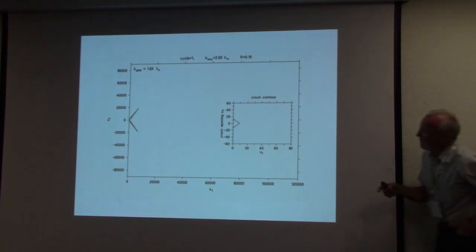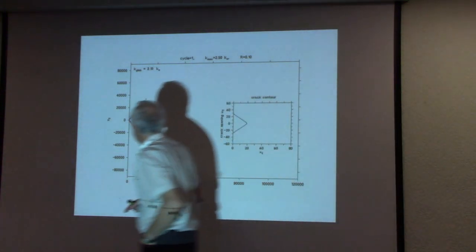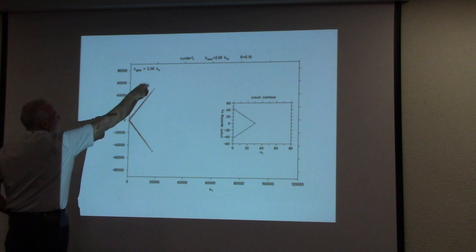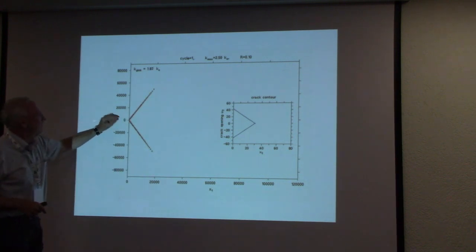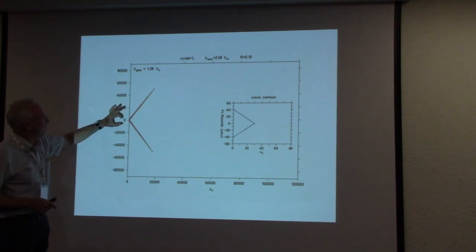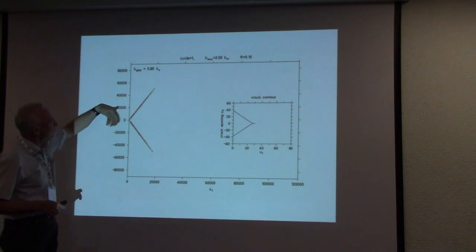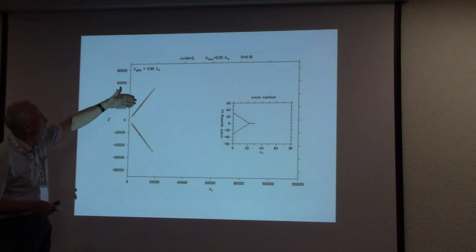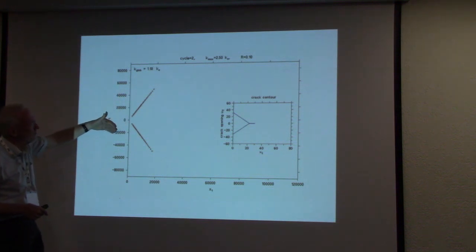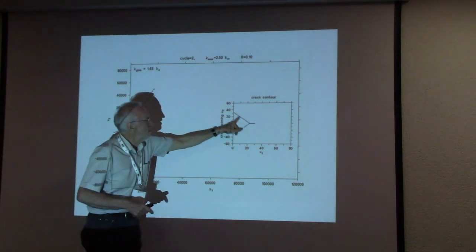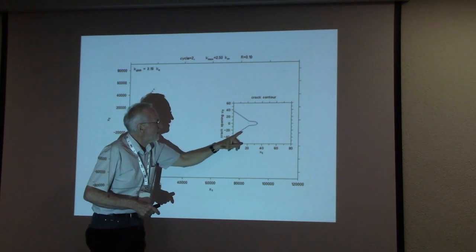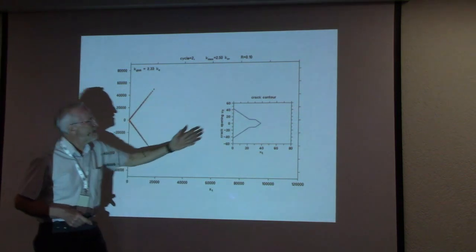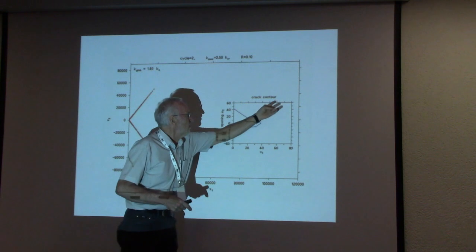This is what happens when we load, for example, a crack. It is really taken into account only that you need a certain friction stress so that the dislocation can move. If you unload the crack, dislocations move back. They form this V-shaped crack. If you load again, dislocations move again away from the crack end.